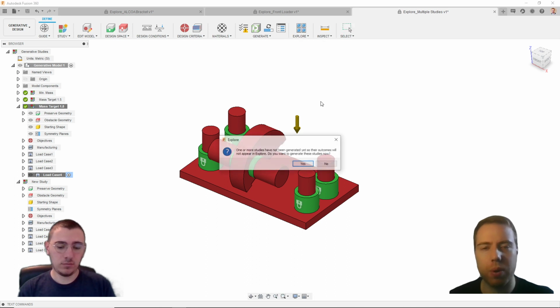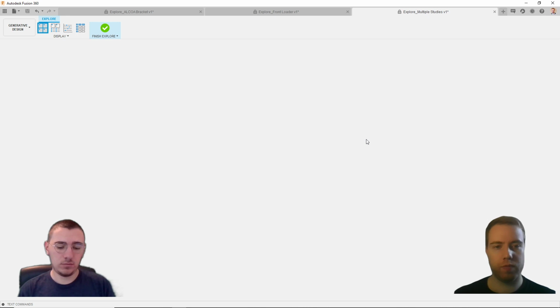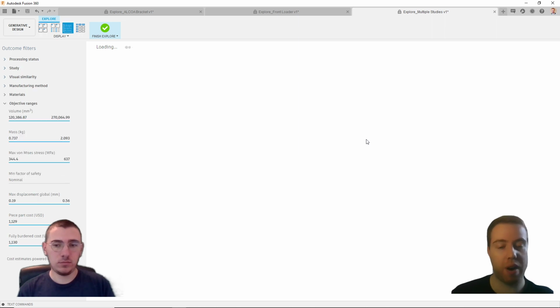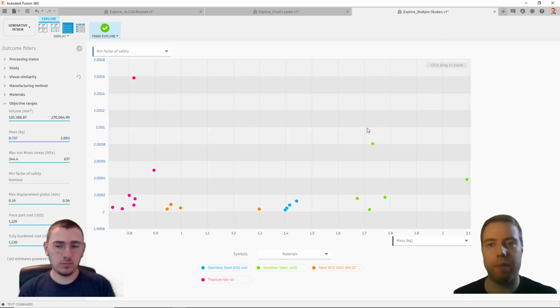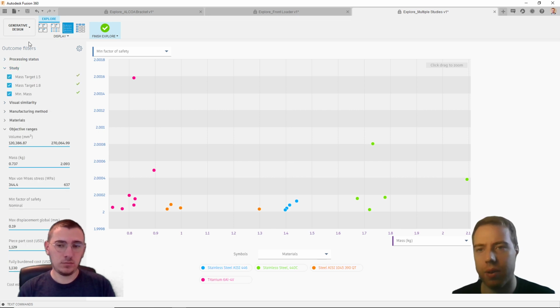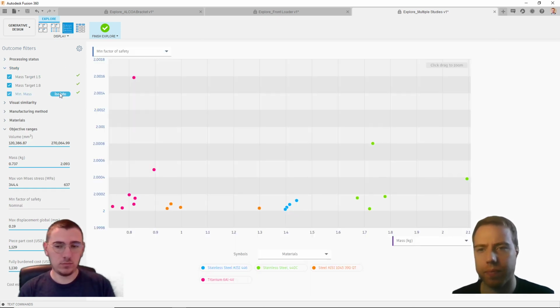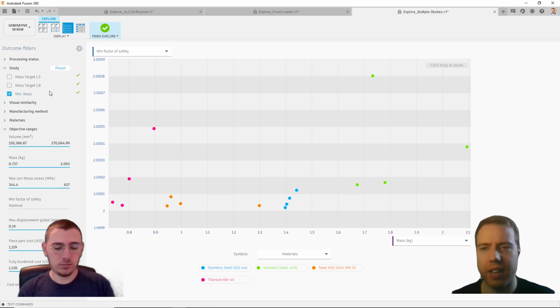So now if I explore the outcomes, you see it gave me that dialog box because I created a new study, and it's just asking me if I want to generate outcomes for that study, which I don't want to do. And if we go into our different designs, we can see we can filter by study. So if I go here. So these are the design outcomes that were minimized mass.